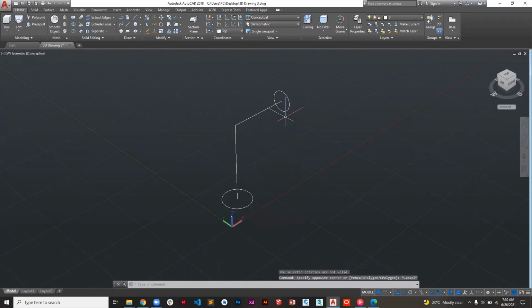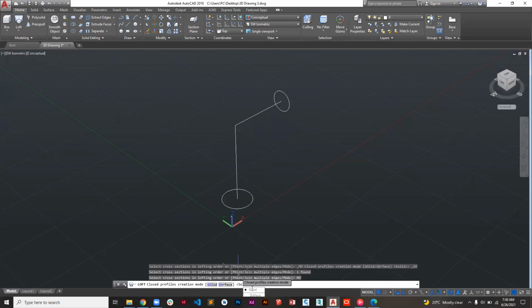Or you choose just one object. You choose one object and the path itself, and the rest is okay. That is for sweep. For Loft, it needs 2 objects. If you select just one and press enter, it will just exit. Anyway, I'll find out and see why it isn't.